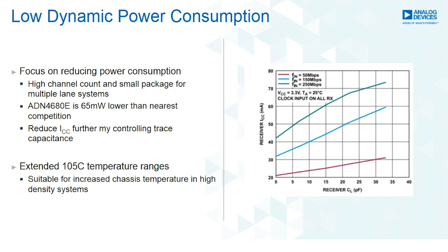The graph on the right shows why the low latency on M-LVDS is an advantage. So in SPI, you have a limited time period of a half clock cycle for the clock edge to reach the peripheral and for the data to come back. And any added latency eats into the budget and can reduce the maximum clock rate allowed in the SPI. M-LVDS has a much lower latency when you compare it to other differential transceivers like RS-485, so it is well suited for extending high SPI clock rates over several meters.